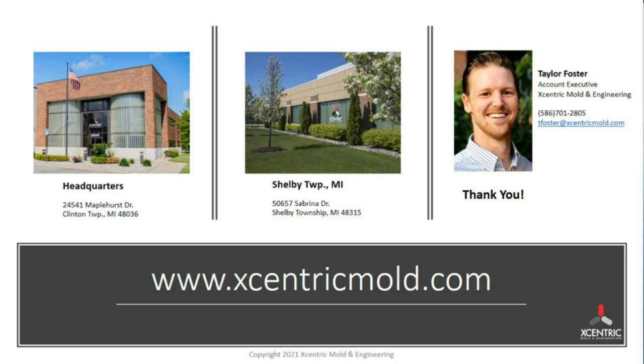I would say, I'm not super familiar with benchtop injection molders specifically for in-house. I would say once you're at the injection molding level, you want to be simulating as close as possible to what you'll be doing on the production level, which would be a real injection molder, typically speaking, overseas or in the U.S. creating steel tooling. So to that end, I would probably steer away from a benchtop injection molder in-house unless you have a lot of expertise on the team with injection molding. I would say probably easier and more cost-effective to bring 3D printing in-house and have a good outsourced partner for injection molding if you don't have either currently.